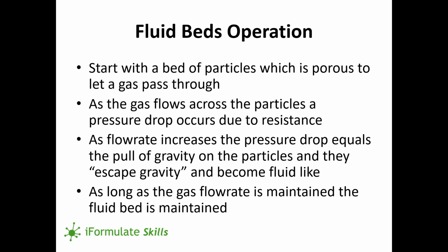The other important difference is that spray dryers start off with a liquid drop and form the particle as it dries. Fluid beds require a particle to already exist, either as a solid or a semi-solid, onto which you can do lots of different transformations. So often you will have a fluid bed at the end of a spray drying tower, taking the solid particles the spray dryer produces, and we'll talk a bit more about that. But basically, as I said, fluid beds have to start with a bed of particles, and that bed of particles is basically a static bed.